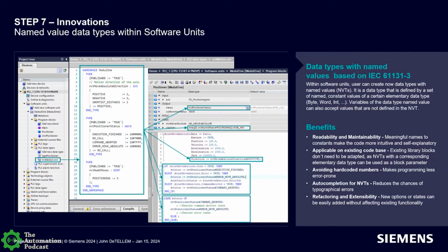Inside the program structure where we can organize our PLC blocks, traditionally we program inside main, OB1, and set up our structure under program blocks. But software units are another way to segment control code into little units that are more object oriented. Maybe module 1 is the conveyor and module 2 is the robots, so I organize a lot more structure in the breakout of my program.